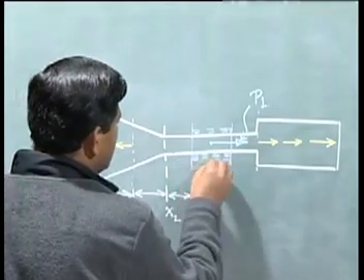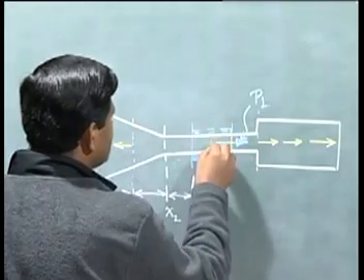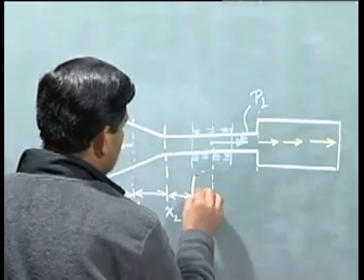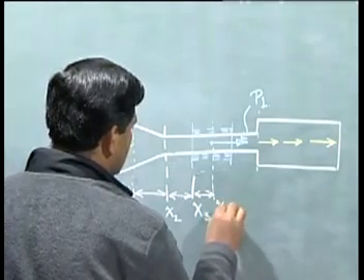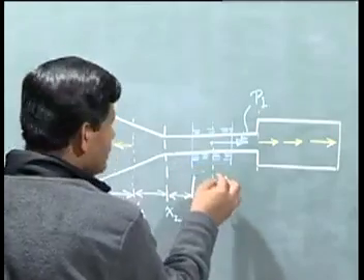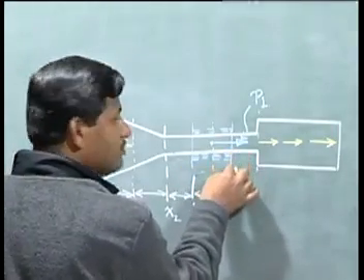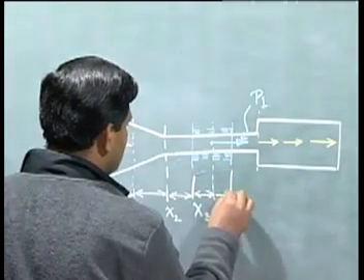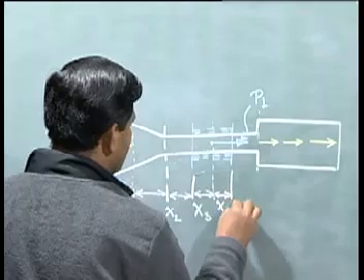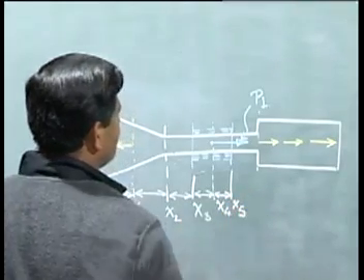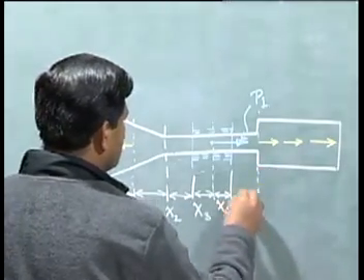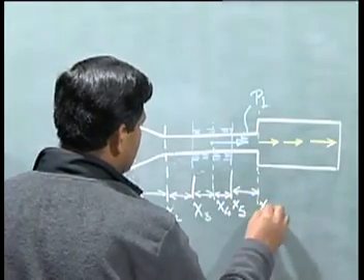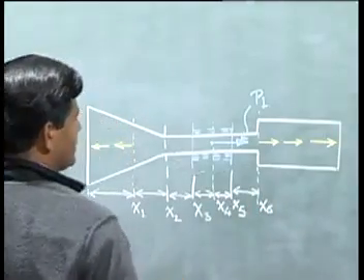Now the fourth one: you see that here the distributed spring is there, but there is a point load here and I have to honor the point load. So the fourth one is this, x4. Then the fifth one, I continue and see that this is the end of the region where the distributed spring is applied. So this becomes x5. This continues till this one, where again the area changes, as x6.